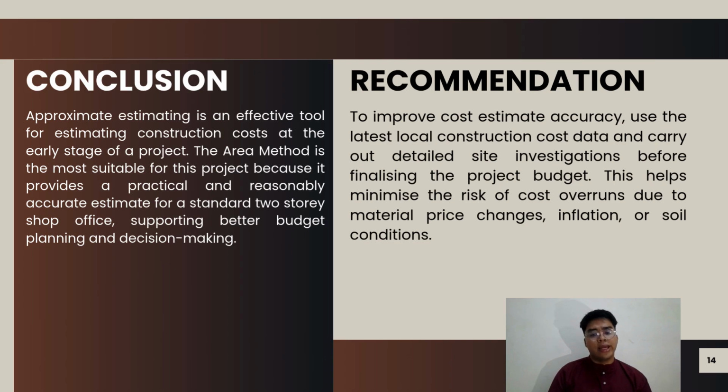To wrap up my presentation, I will conclude that approximate estimating is highly effective for early stage project costing. For this specific two-story shop office, the area method proved to be the most practical choice, giving us a reasonably accurate baseline budget for reliable decision making. To make sure future estimates are even better, I recommend using the latest local cost data and performing a thorough site investigation before fixing the final budget. This will protect the project from risks like unexpected soil condition, inflation, or sudden material price change.